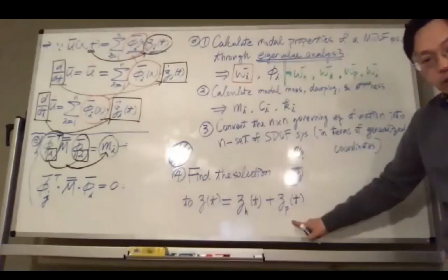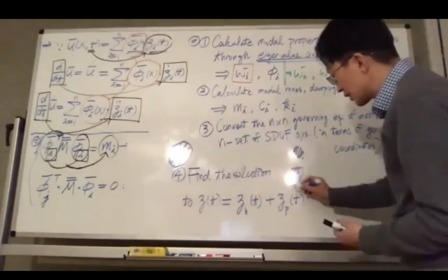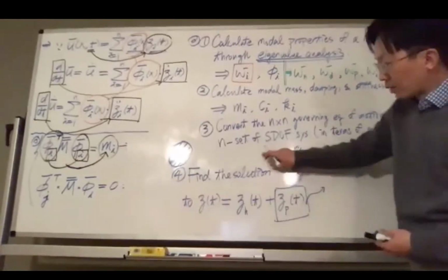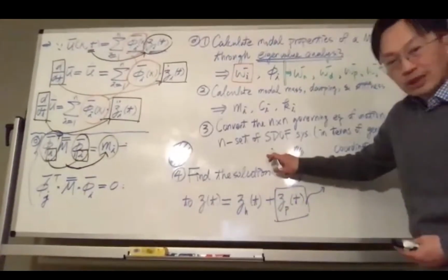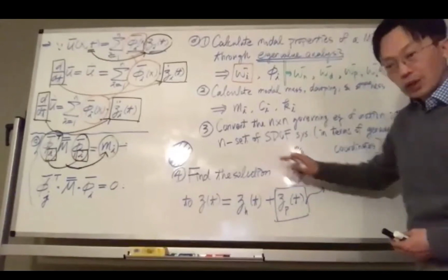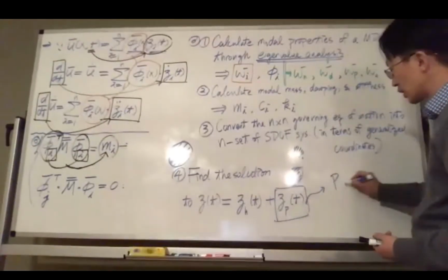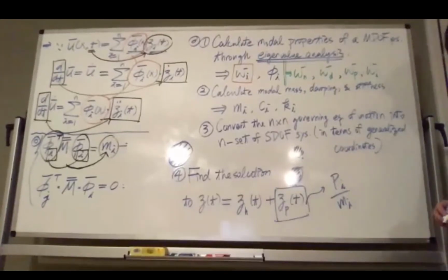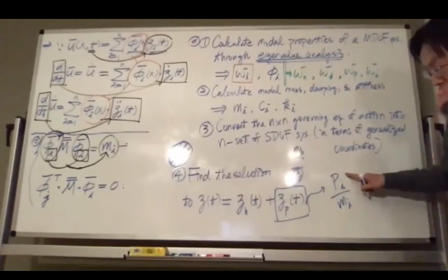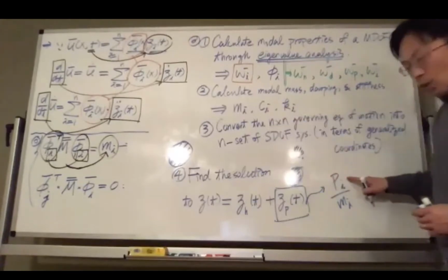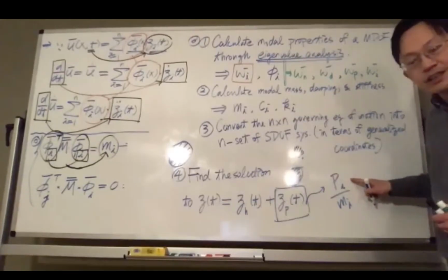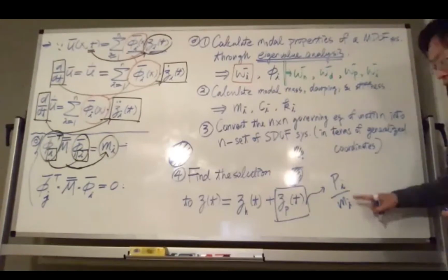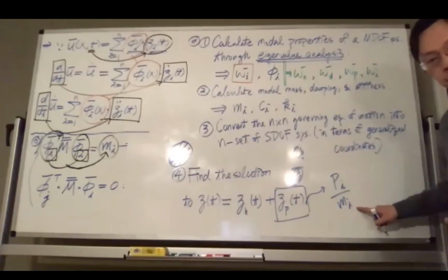The particular one here, you have to be careful because this is the solution when that particular degree of freedom is subjected to what we call modal loading. And the modal loading is usually denoted by pi over mi. So this pi, again, once you finish the conversion, no longer carries any physical meaning. It's in the modal space. So this is the modal loading divided by modal mass.